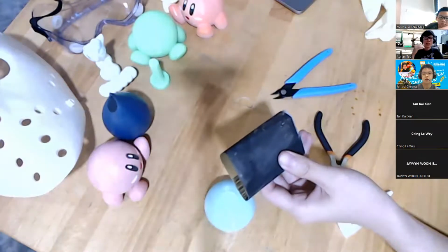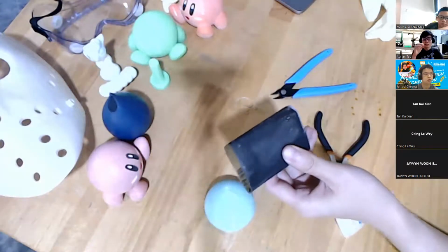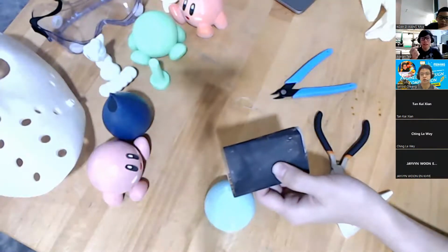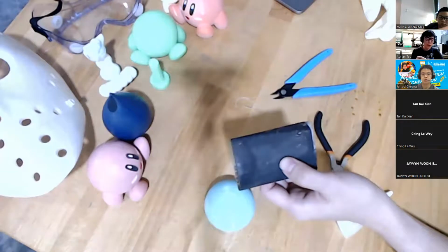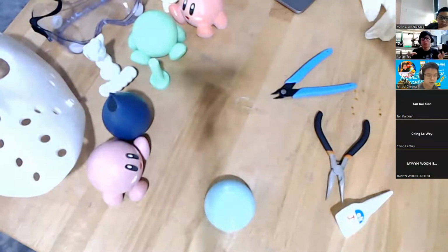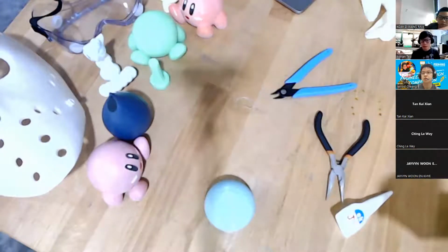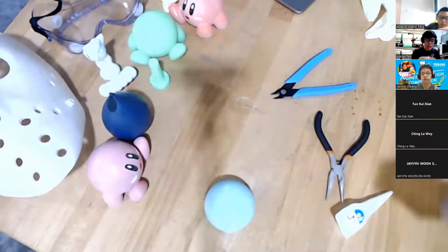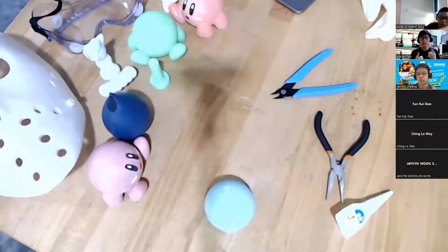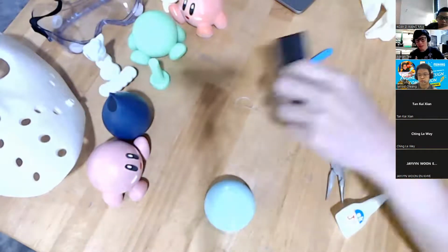As you go higher and higher, the number, the particle that you sand, the plastic particle will be smaller and smaller, finer and finer. So having water means that the particle will straight away enter the water. When you sand, all the plastic and everything will stick together with the water. It won't fly everywhere. That's why you use water sanding when you go higher grade. Okay, because you don't want to, again, you don't want to inhale all the plastic into your lungs. All right.